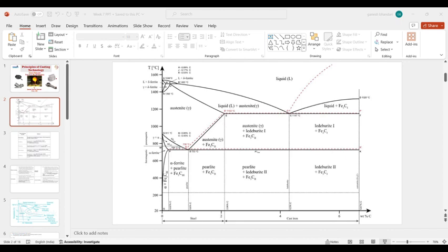So we generally go with brine solutions or oil. But the disadvantage with oil is that sometimes oil catches fire during quenching. So you have to consider safety also in that case, and go with very high safety equipment during the oil quenching process. So industries generally prefer brine solutions because they provide better properties compared to water or oil: it is not going to evaporate that easily and it will not catch fire. So that is the advantage of brine solutions during the quenching process.